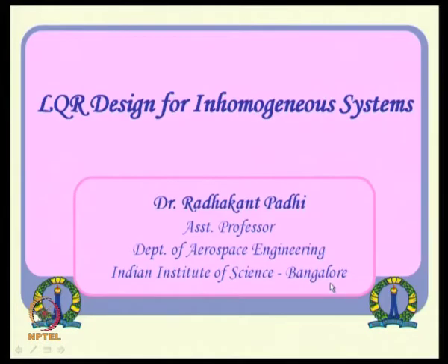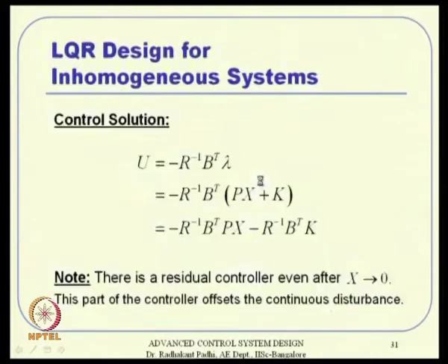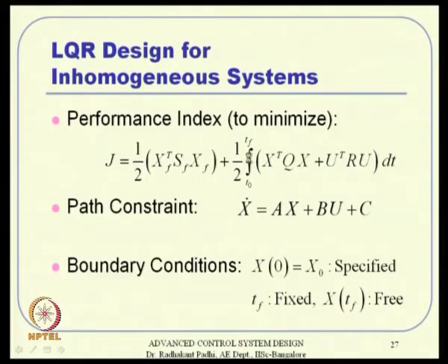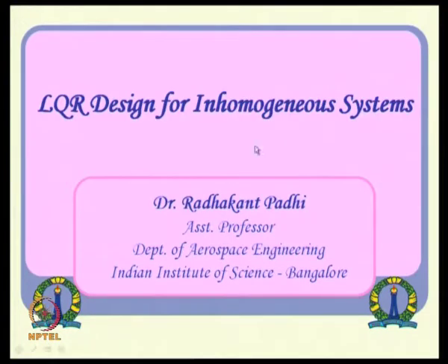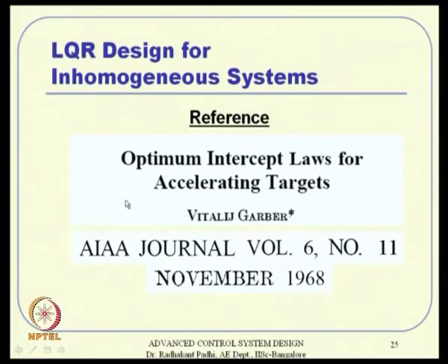Okay. All right. So, next we see LQR design for an inhomogeneous system. I have taken this from here. Obviously, this idea is not very new, all these ideas are not very new, people studied this a long time back, but they are still useful in a variety of conditions. This is also an aerospace application. Those of you who are interested in how this formulation is useful for missile guidance can see this paper, and they can see the utility of this for missile guidance problems.